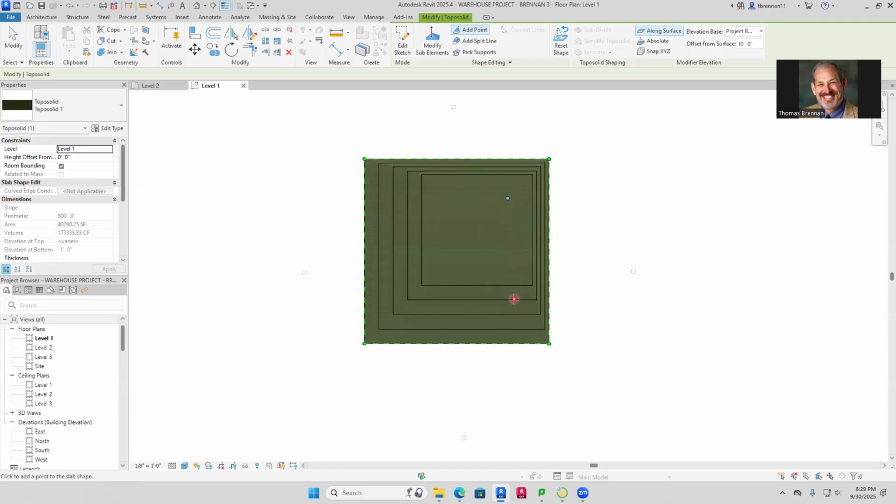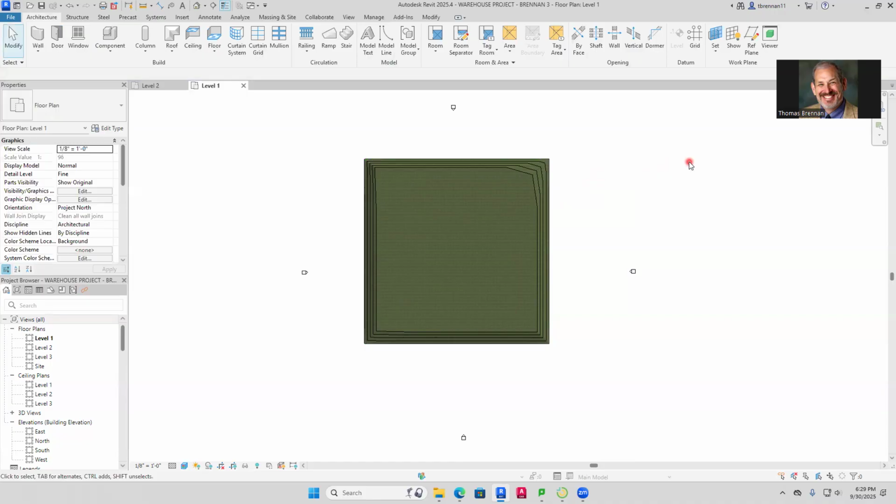And then you can bring it down here and do it again and click there. And then you can bring it over here and look at the shape. The topography is kind of like this. Just pick 4 corners like that. And when you do that, you have just added those high points. Okay, so that is what you created. Now we're deliberately keeping this simple. Topography is not usually this forgiving, but that's what we have here. Now to get out of here, you press your escape key twice. When you press your escape key twice, you're out of there.